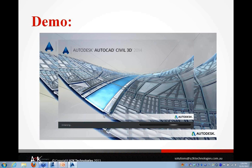I was wondering about the crashing that I was having before, where it hadn't crashed before. I wonder if it's because I've got Infrastructure Modeler running in the background that's using perhaps a lot more memory than what it normally would with a file of that size in there. Perhaps. I'll just close it down and see if that makes any difference.